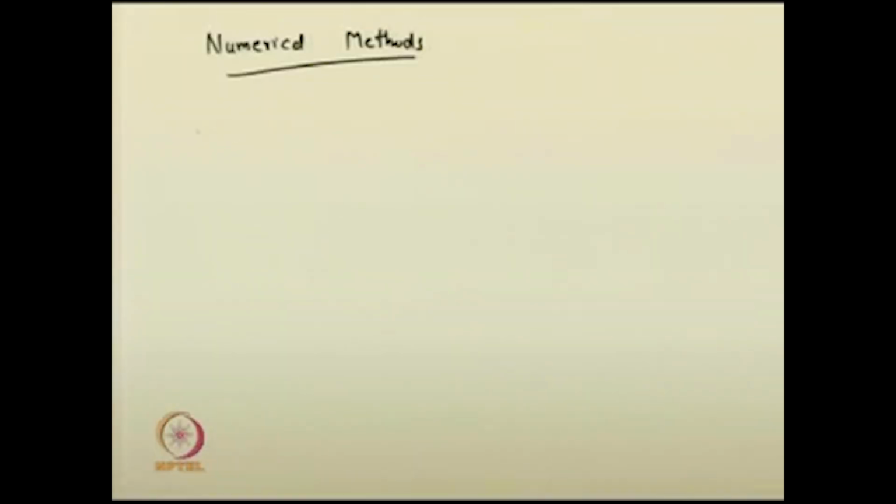So, let me tell you. In the numerical methods for open channel flow, using numerical methods we can find the distance between two sections if depths are specified.